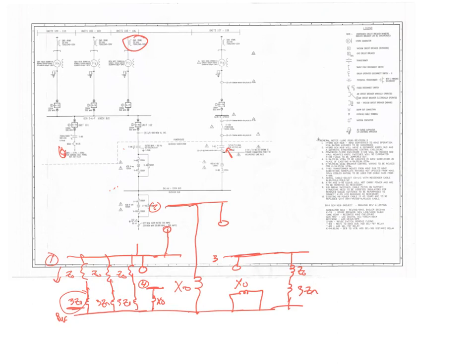So now, my Y bus for my zero sequence, and if it's helpful, 1, 2, 3, 4 and 1, 2, 3, 4. These are the self-admittances. So here's the other very important thing. These elements here, this one and this one, are in series with each other.